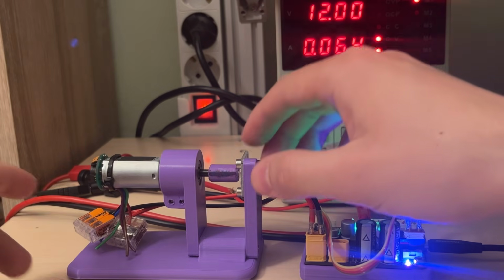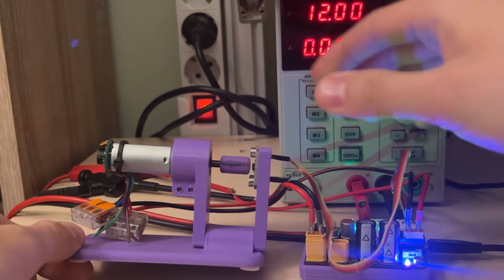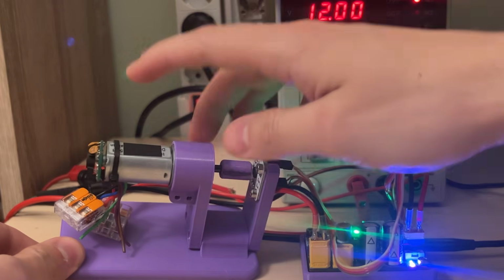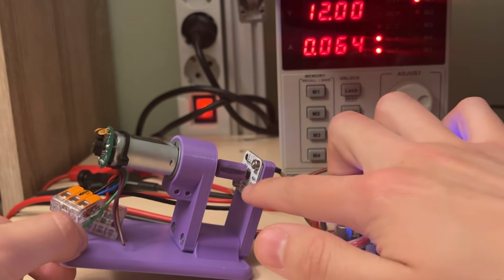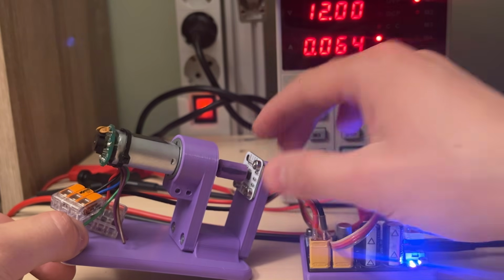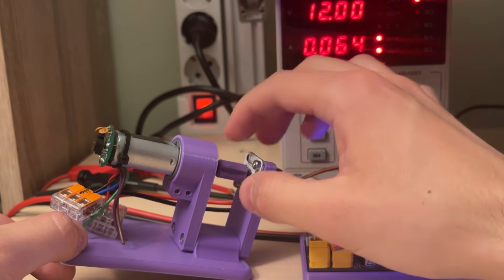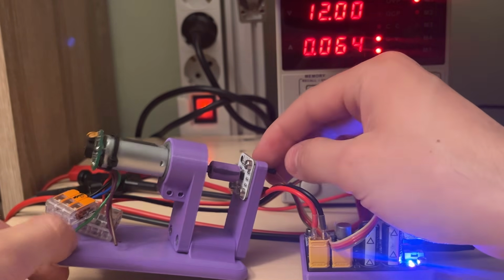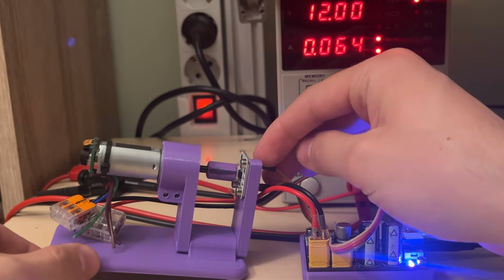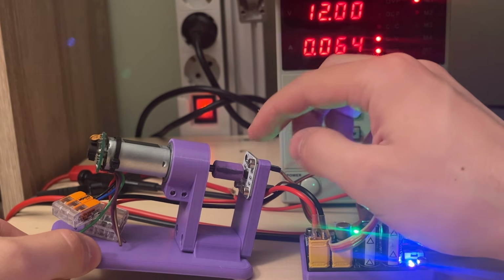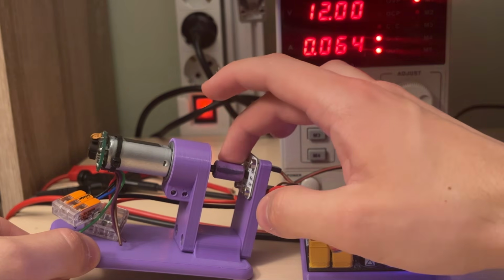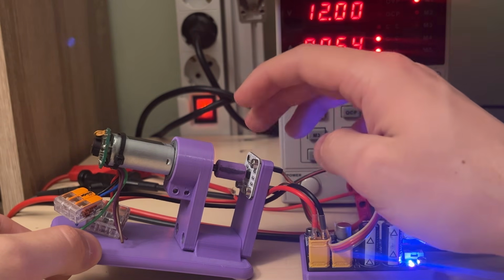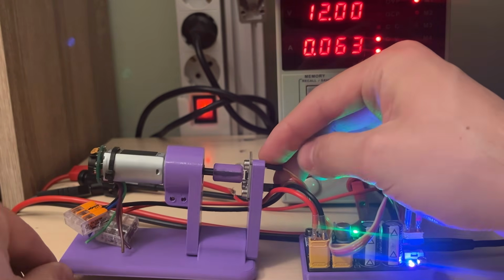Now it's time to see in practice everything that we've just talked about PID controllers. On your screen now you can see a small DC motor that has a magnet on top, and it's pointed directly to this little board that has an encoder on it that detects the field from that little magnet, and that's how it tells the position. So all you need to know for now is that this sensor somehow gives us the angular position of this motor, and we'll talk more about types of encoders in the next video.